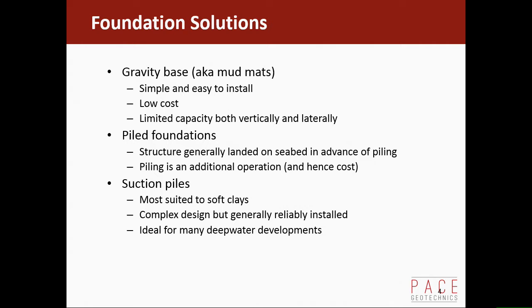Sorry, you mentioned the friction angle. Is it when the friction angle is small or when it's large that it will slide? If you've got a high friction angle, it's less likely to slide. Just more friction, basically. But it's also a function of the weight. It's the weight times the tangent of the friction angle that gives you the sliding resistance. Okay.